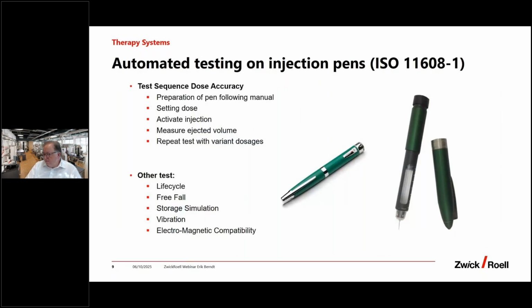The normal standard for sure requires the test of the full device filled with the drug. And at the end, for sure, the key test out of this is the dose accuracy on different settings, and the dose settings of this pen itself.